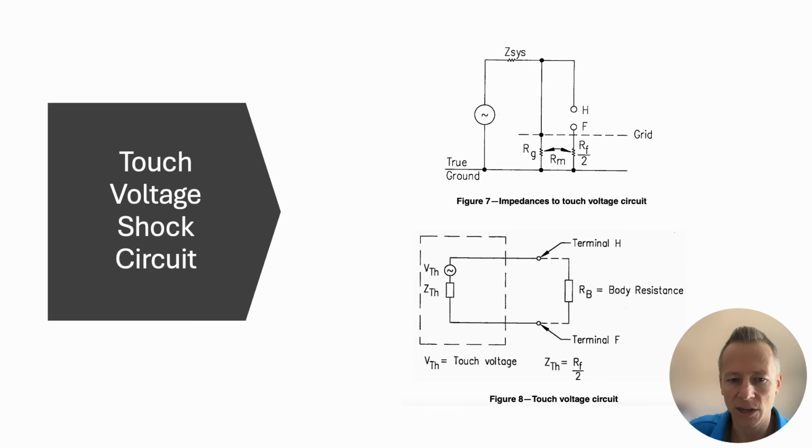But so then you come up with what the tolerable voltage is that the person can take for the duration, right? So in grounding studies, we come up with a duration of how long the fault and how long the shock would last based off your body resistance. And given that and this Thevenin resistance that you come up with here, and how your feet connect to the earth determines how much, and again, it's open circuit voltage that we evaluate with, but what would be the voltage required to drive that amount of current through the body.